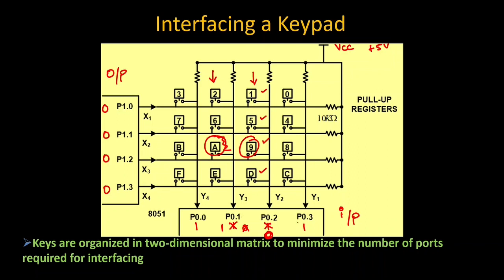Right? So as a rough idea, just have a conclusion. If I am going to give the value of 0, 0, 0, 0, understand these are going to be your lower nibbles, right? Why am I saying it is lower nibbles? Because it is going to be data 0 to data 3 and D4 to D7, right? So I have said it is going to be port 0.0, 1, 2, 3, right? So whatever I am going to concentrate on is the lower nibbles.